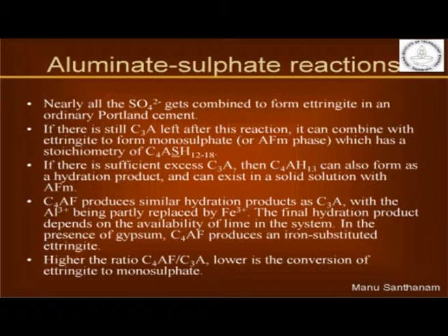Now why is this sulfate resistant cement actually resistant to sulfates? Because when you have external sulfates coming into this system, the ettringite is already stable in that system, so it does not react. But when the sulfates come into a normal Portland cement system, the sulfate will react with monosulfate and convert it back to ettringite. Now this conversion is happening when the concrete is already hard. That means this ettringite is going to expand inside hardened concrete, that's going to result in cracking.